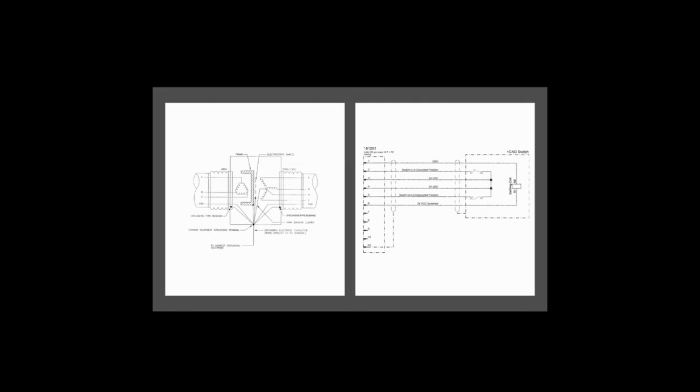Also, the outer terminal will be connected to the chamber that has its own specified copper rod set up in the chamber. The chamber resistance must be lower than 2 ohm of grounding resistance to avoid unwanted current floating and damaging the apparatus. If there is any lightning involved in this situation or any other situation, there is a special device that must be connected to the grounding system.